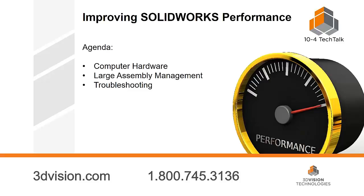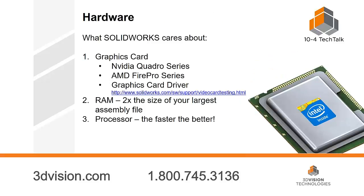of improving performance for our customers. So computer hardware: a lot of people ask what the important factors in hardware are that SOLIDWORKS really cares about. The first thing is your graphics card. SOLIDWORKS has a website that lists which graphics cards are approved. Really, as long as you have an NVIDIA Quadro series or an AMD FirePro series, or there's actually a couple others as well, you're usually okay for SOLIDWORKS.